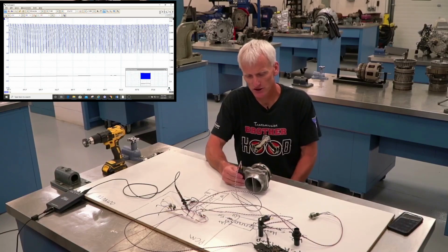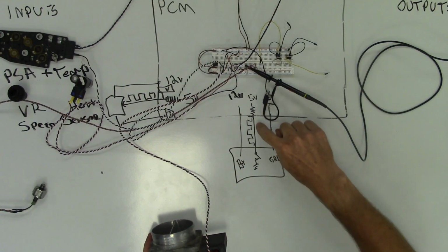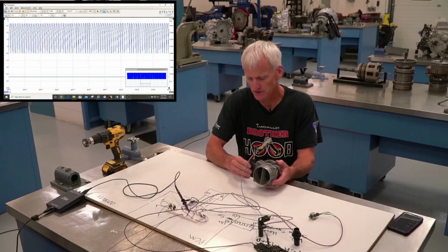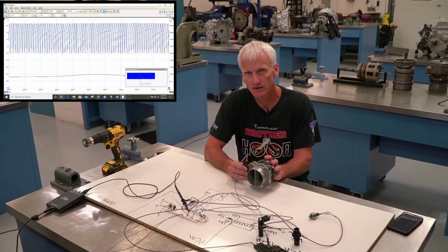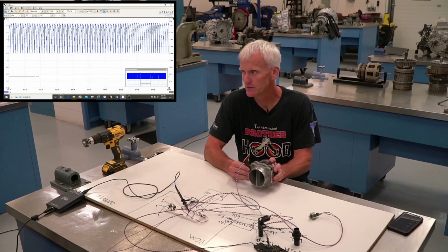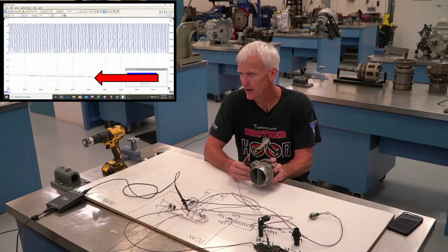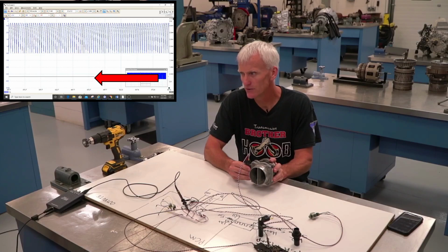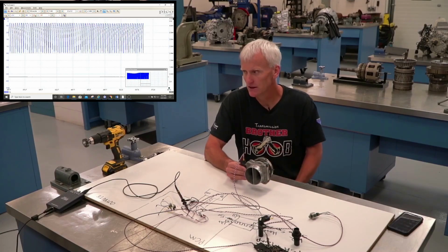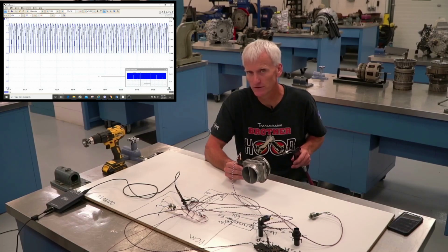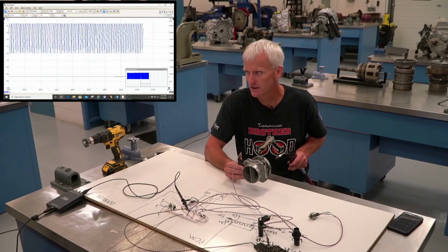Okay, so I've got my GM sensor wired up, got power and ground. I got 5 volts going through a 100,000 ohm resistor, and it's switching. The sensor is doing its job switching that. It will change the frequency based on the amount of air that's flowing in. And on the scope image that you see, you actually see the frequency of it just sitting there. And that bottom black line is actually showing the frequency. I did a math channel, and it's showing the frequency that it's measuring. You can see when I start blowing air through it, not only does the frequency change, but you'll see the black line kind of change as well, indicating that.